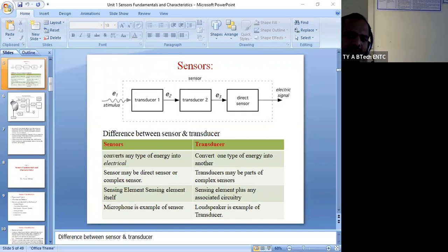Okay. So see here, in this diagram, we have shown 5 different inputs: 1, 2, 3, 4, 5. Sensor, any object, excitation circuit meaning generation of some electrical signal. Okay, CTPT may be there. You know the meaning of CTPT, current transformer, potential transformer, that is measurement of current and potential, that is voltage. Interface of any device, like relays are there, some switches are there. Out of that, the multiplexer will select one output at a time. So see, I have 5 inputs at the multiplexer side and 1 output at the multiplexer side.